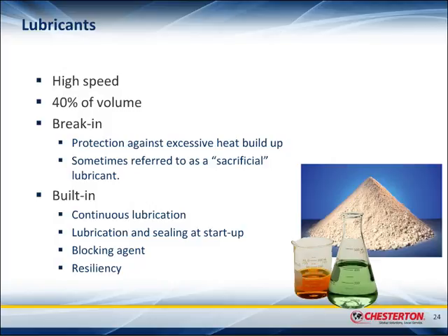So lubricants increase the speed capability of the packing, and they can make up approximately 40% of the volume depending on the packing. So actually a pretty high percentage of the actual volume can be taken up by lubricants.